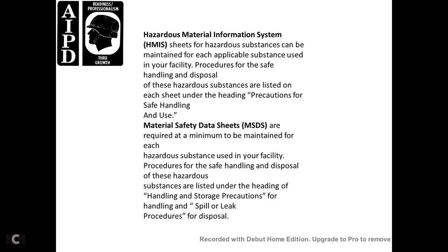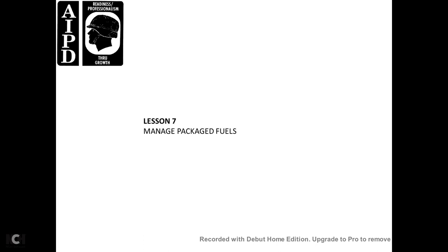Your material safety data sheets, MSDS, are required as a minimum to maintain with each of the hazardous substances within the facility, proceed with the safe handling and disposal of the hazardous substance listed on the heading with the handling and storage precautions, the handling of spills and leaks, with the procedure for the disposal.